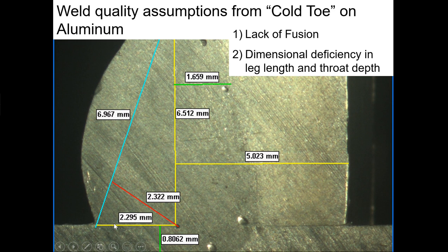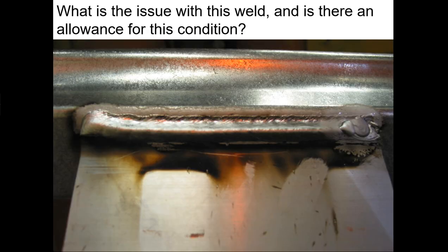It will only stick to the areas that are hot enough or liquefied. This means you've added too much filler material and it's built up based on what we need. So the leg length would be deficient, and the leg length is going to require restoration by adding it right in here. Again, referencing your prototype, your shop floor sample for size.